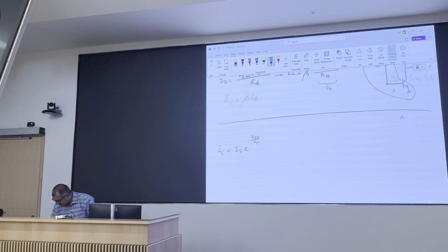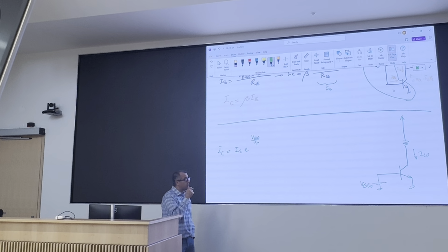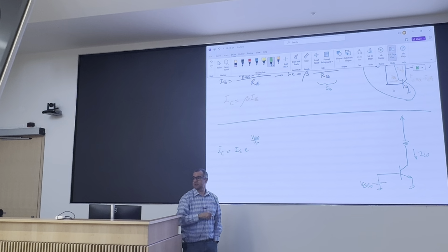So here is the circuit that we propose. Some VBE not that gives you the desired IC. But at this point, you've seen a few of your colleagues get killed, so you don't pay for this. Right? So you go and say, okay, I need a voltage here that is this much. A cheap way of producing the voltage you like is to take a large voltage and use a voltage divider, a resistive voltage divider. Right?